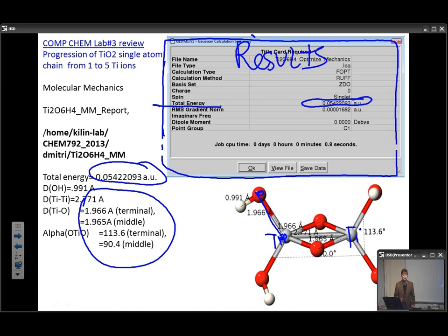Yes. How to measure? Excuse me, can I ask a question? How to measure the distance between two atoms? Is there a menu or where? Measuring distances and angles: if you are modifying a distance in GaussView, you see a bar menu that you can move forward and back, but if you do not move it and just look at the value near this bar, it shows the distance or angle. Oh, it is the simplest way. I was trying to do the same. Here, in that picture, I can see the angle and distance of the bond.